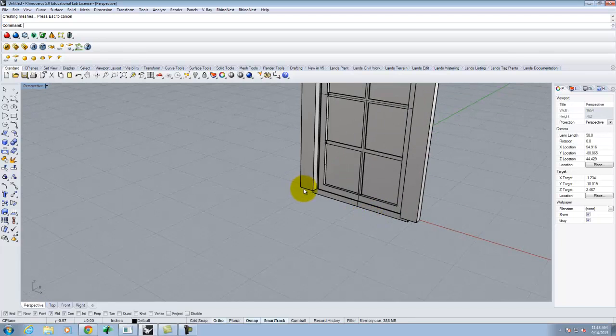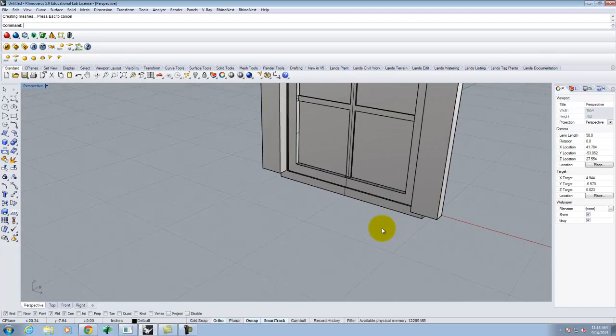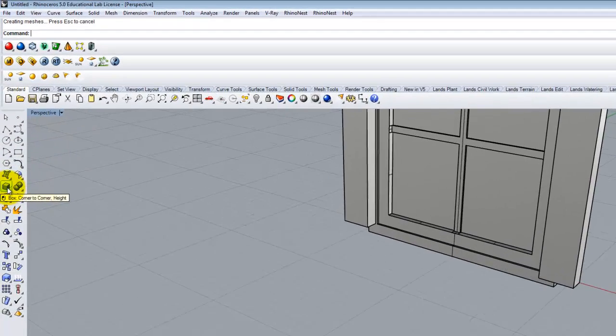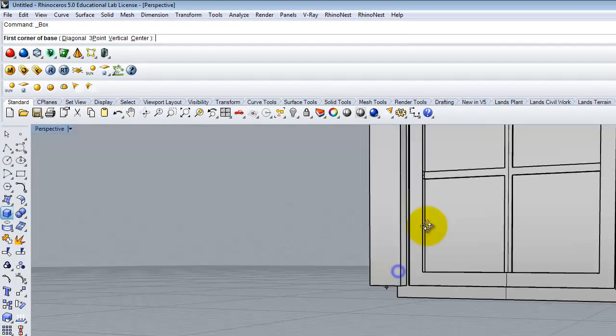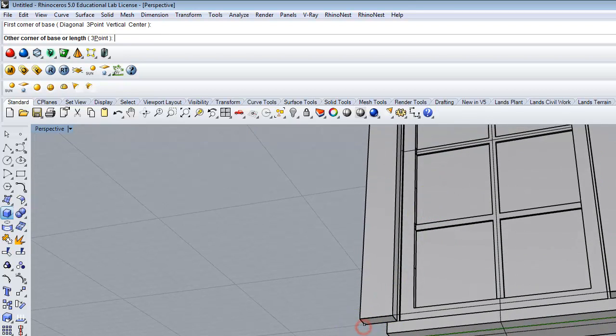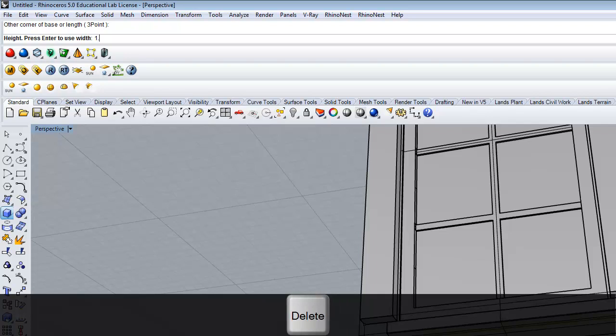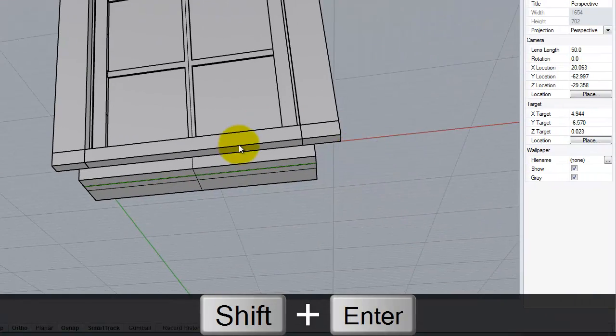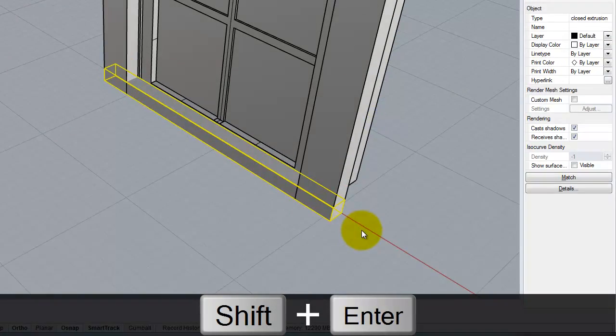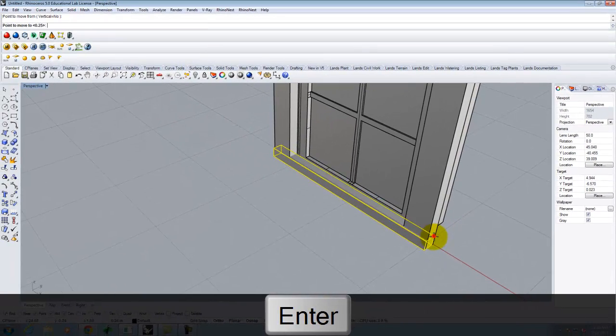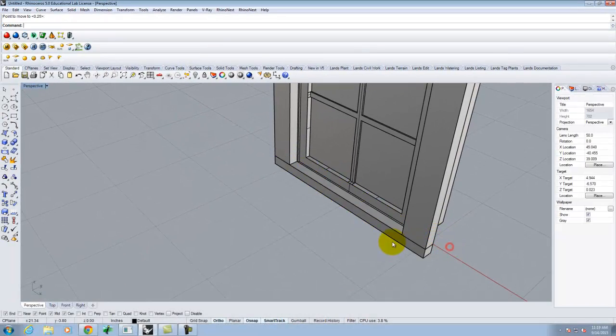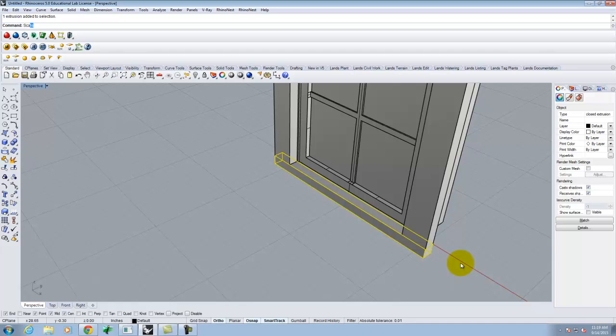Okay, I can do the same thing down here for maybe a window sill. All right, so let's go something like this. Go from there, and we'll go 1.5 inches. Oops, wrong direction. Should have been negative, but just move it down. And I want that still to stick out a little bit, so let's do a scale 1D.